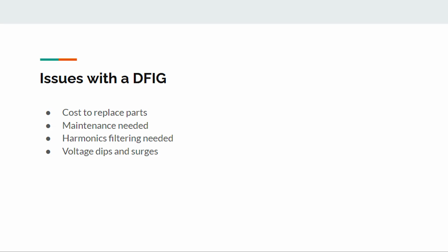Harmonics play an important role when it comes to steady state power as well. The DFIG involves PWM switching to create a DC link between the rotor and stator, which can pose noise and must be filtered. Low pass, band pass, and high pass circuits must be used at both the stator and rotor side of the DFIG.